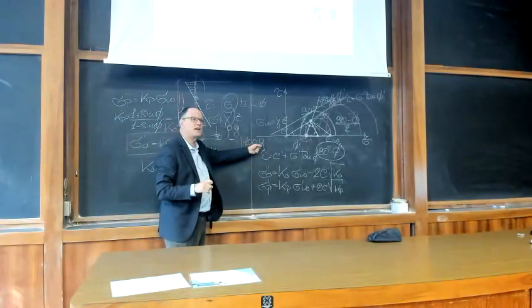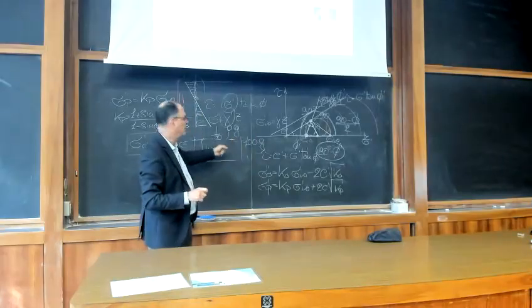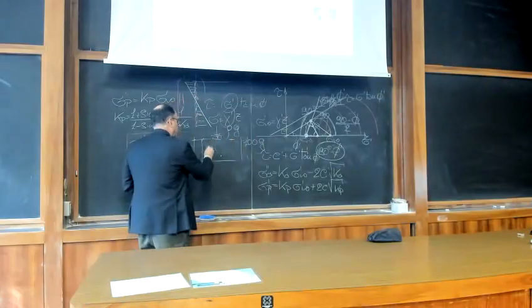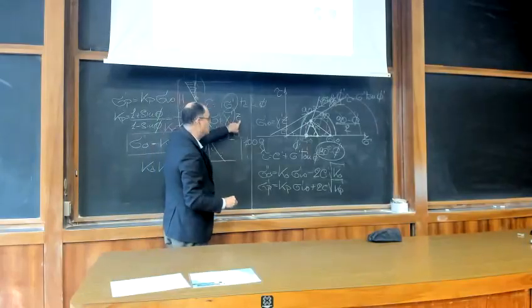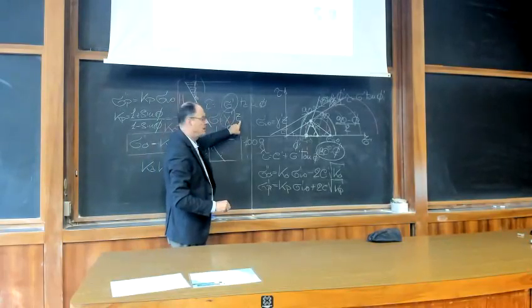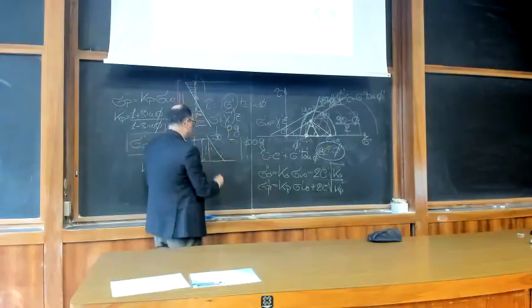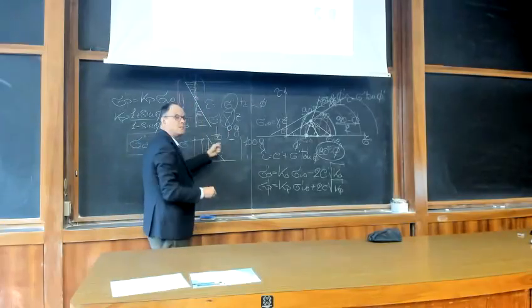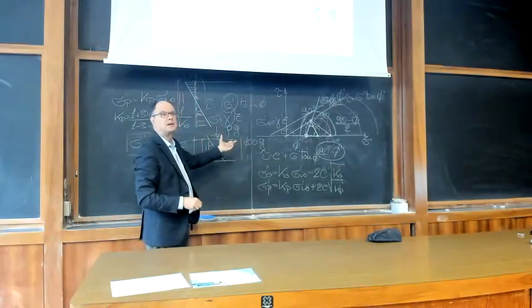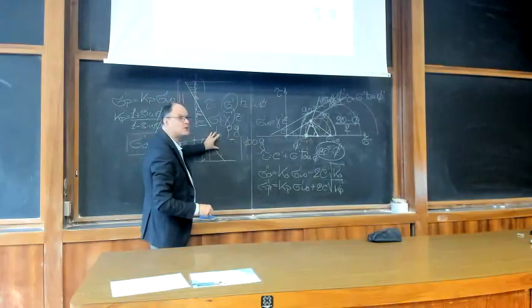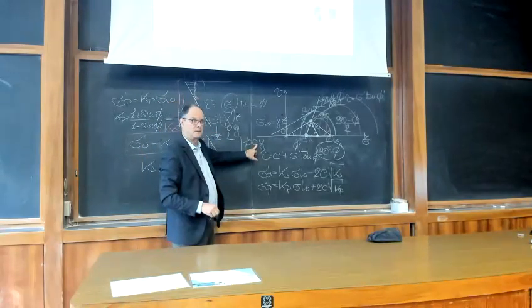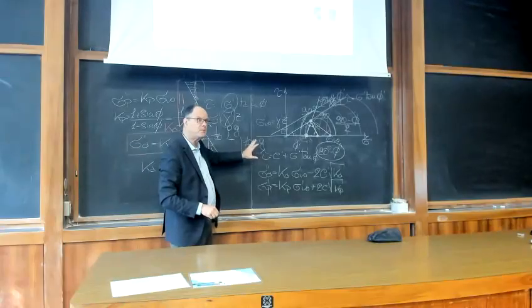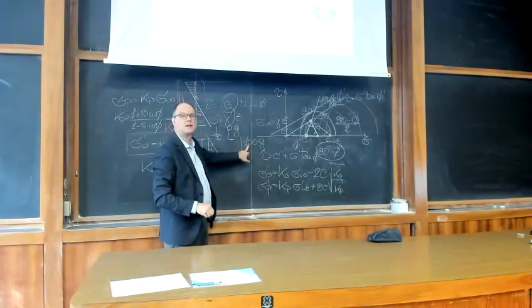And this will generate a gravitational field which is still distributed linearly, increasing linearly with z, but with a slope which is 100 times the normal gravitational field. And this means that 1 meter will be 100 meters. The same stresses that I have under 100 meters.